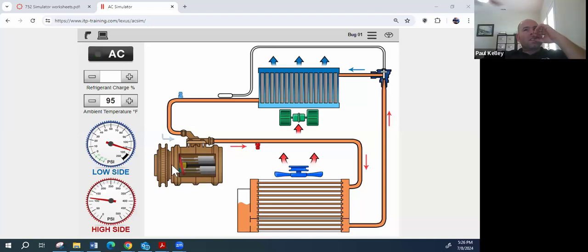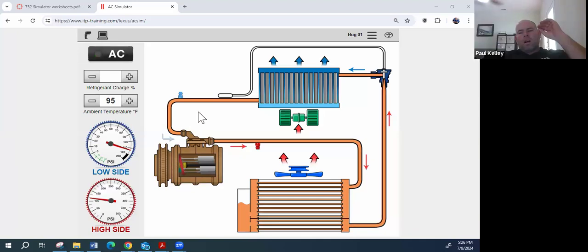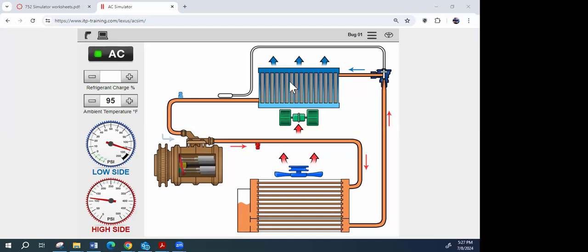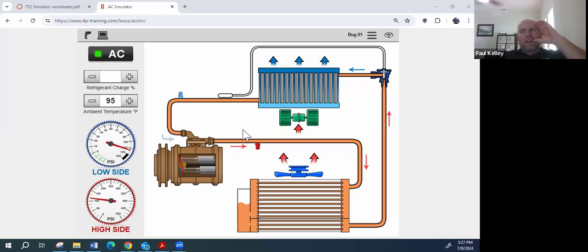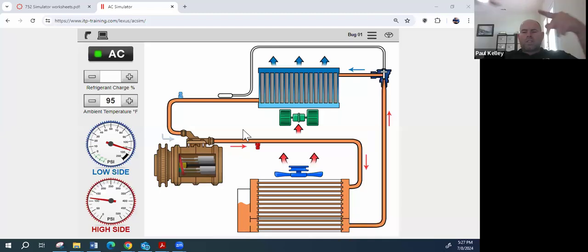Power. Okay, and I agree. Luis, how would you verify that? Either the fuse or the relay. Yeah, but how would you verify it? You tell me components, tell me your test, tell me what you do. You could just check if it's getting voltage at the fuse or just swap out the relay. True, you could do a relay swap. You could check voltage at the fuses.